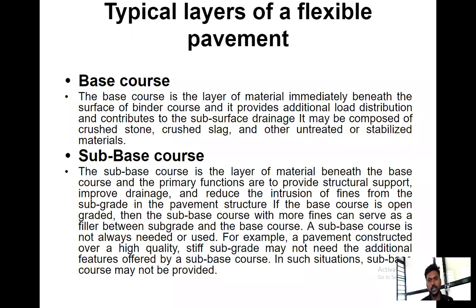Similarly, for the subbase layer, the purpose of the subbase course is to transfer the load from the base course to the subgrade soil. Likewise, the load transfer mechanism will be there in flexible pavements. And in the base course, we are using crushed stones, crushed slags, and other untreated or stabilized materials.